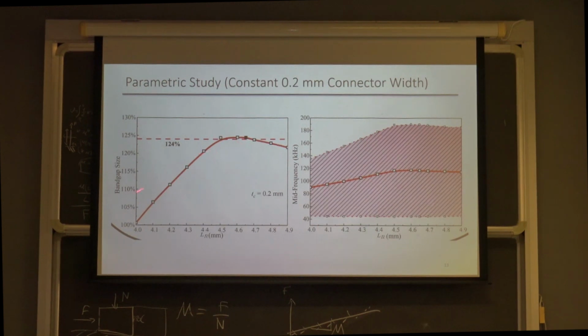And then we changed the local resonator size. If we make it smaller, the square that you saw, then in this case it monotonically decreases, right? So no surprises here. This is something that is well known. However, then we discovered this plateau here where the band gap thickness size would not change much. And moreover, if we increase it even more, it will go down, which was an unexpected and interesting phenomenon,